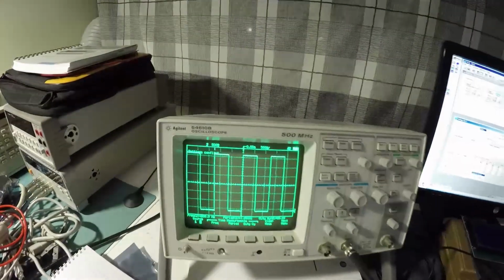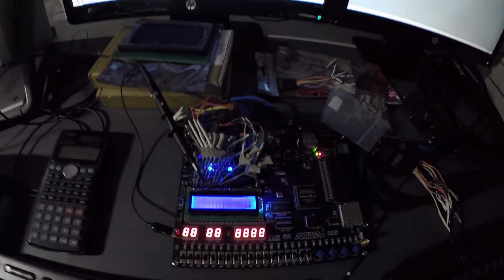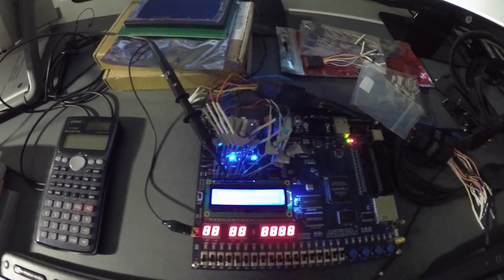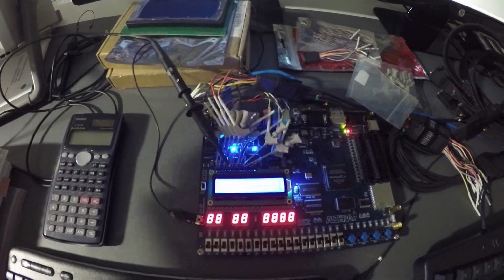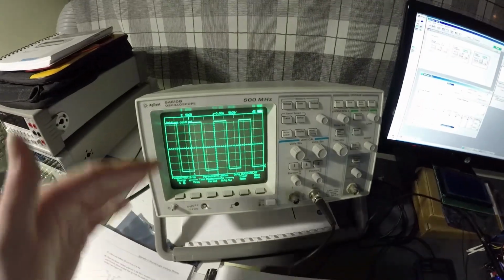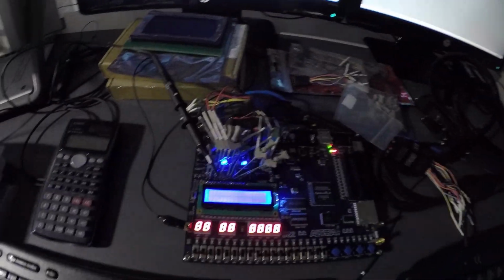The frequency is too high for it to process, and so a 1600 hertz clock for that enable line is just too high, which is one of the main reasons why the 400 hertz signal was chosen in the past, just to bridge that speed requirement for the LCD display.